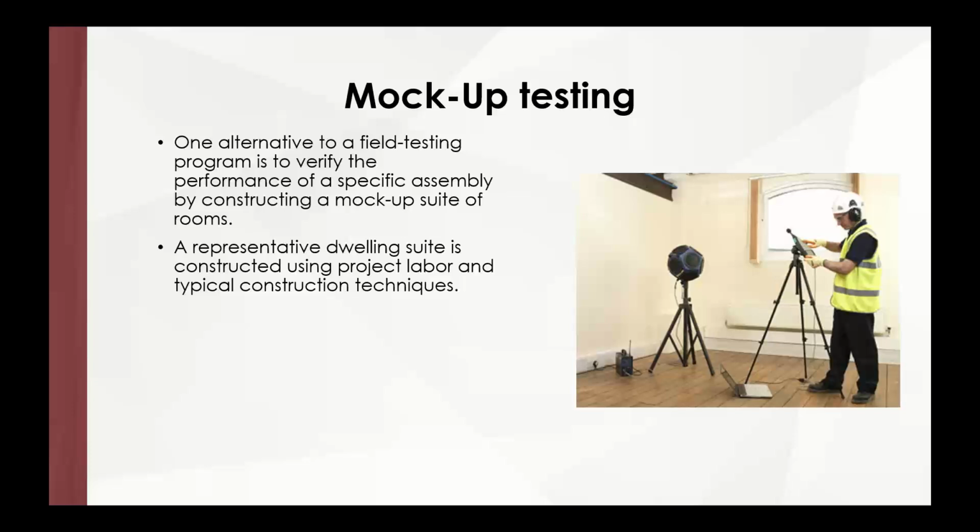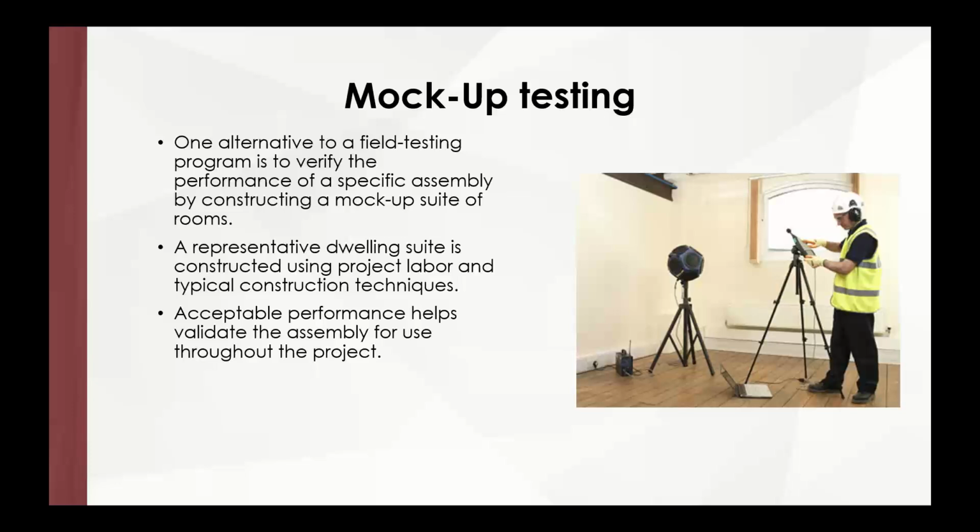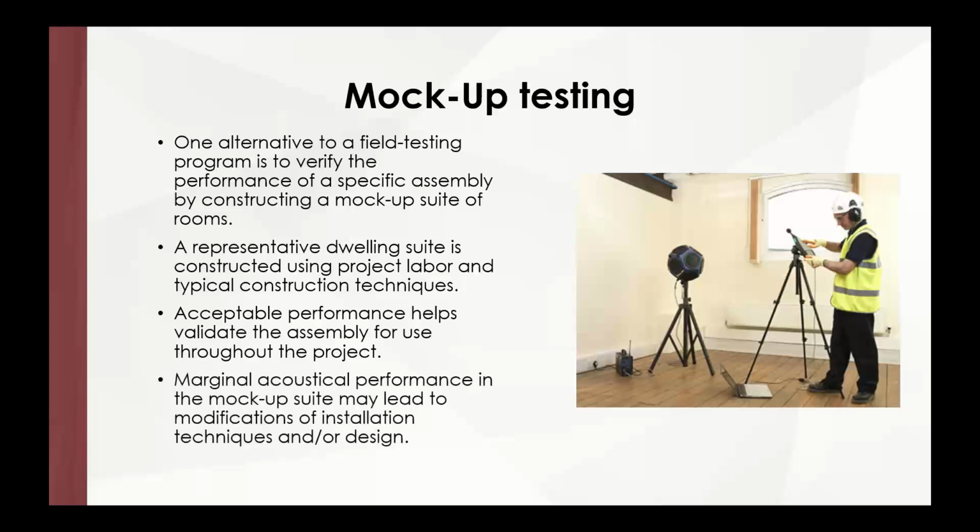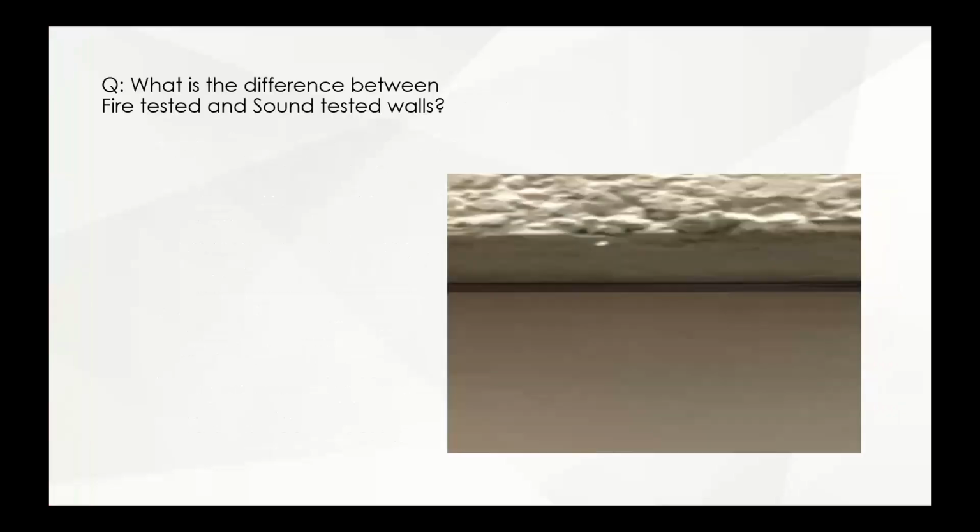And hopefully you have everything in there, the penetrations, the windows, everything else, and get a mock-up test, because acceptable performance is going to help validate what you're building. If it comes out and the number's good, everybody knows this is great, you're going forward. However, if it doesn't perform well, then you may have to switch that assembly, and it's way better to know it in the beginning than halfway or three-quarters of the way through the job.